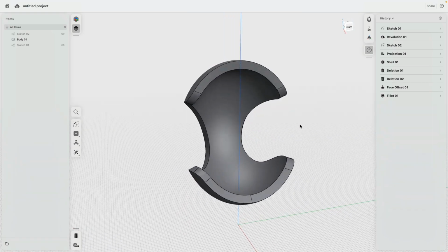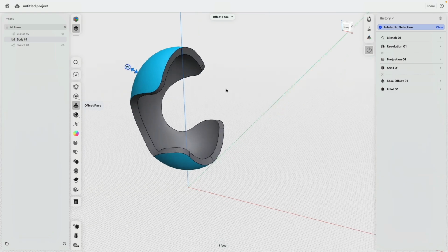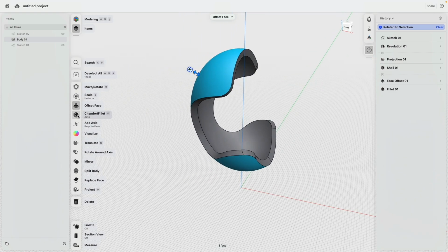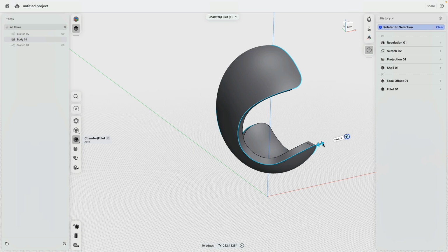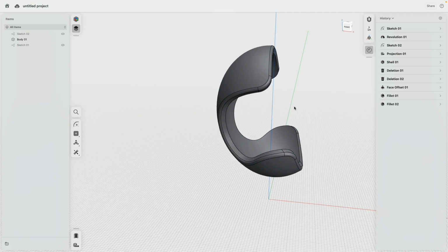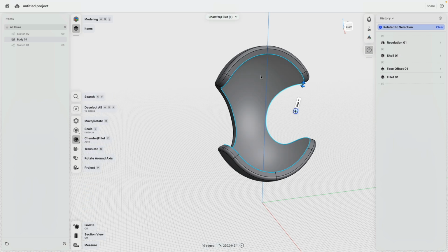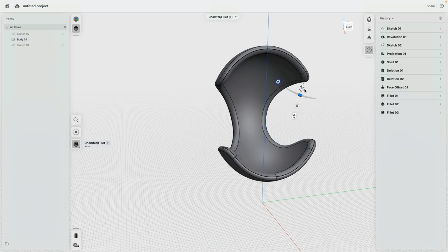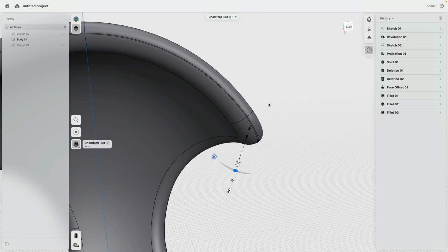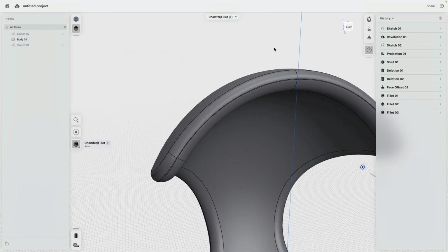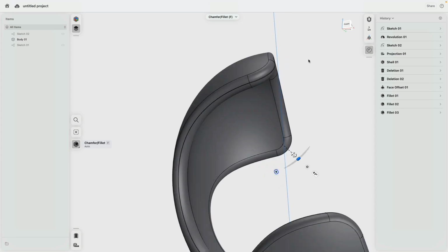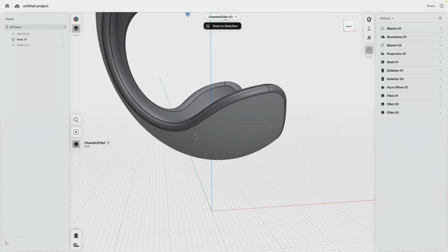5 looks pretty good. And then I will select the outside surface, click chamfer, fillet. We can round this a little bit. Let's say 1 inch. Does this work also on the inside? Very often it does. So by selecting the face and then going to chamfer fillet, you see it selected all the edges. 2 inches. There we are. Pretty cool. And then we have this very thin sliver there, which I'm going to show you a fun trick later on how we can do something with that.